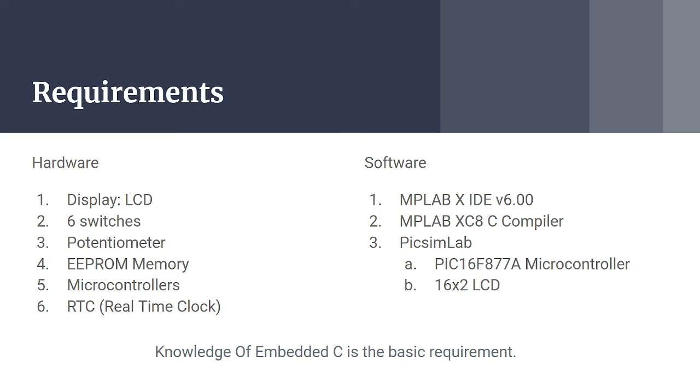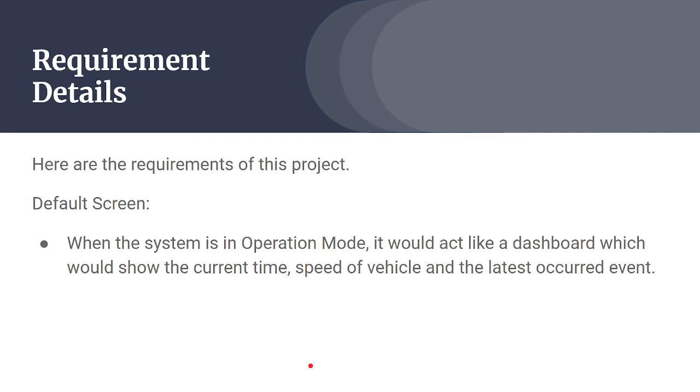Now let's see requirements. In hardware we require LCD display, 6 switches, then potentiometer, EEPROM memory, microcontroller and real-time clock. For simulation software we require MPLAB X IDE version 6, then MPLAB XC8 C compiler, PICsimLab with PIC16F877A microcontroller and 16 by 2 LCD. Knowledge of embedded C is a basic requirement. Let's see requirements in detail. So here are the requirements of this project in detail.